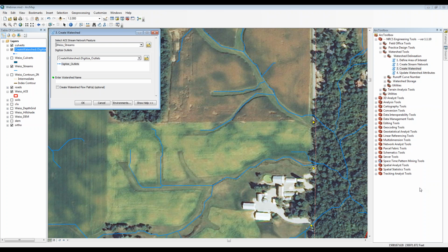I didn't do that very well. Okay, to digitize our outlet, I'm going to draw a dam at the watershed outlet. I need to at least, at a minimum, cross my streamline, but I also don't want to extend my line too far because the entire area contributing to the line will be delineated. So if there's, I don't know, a small flow path that's going through here but not really dumping into my waterway, it's going to be caught if I make my dam quite large.